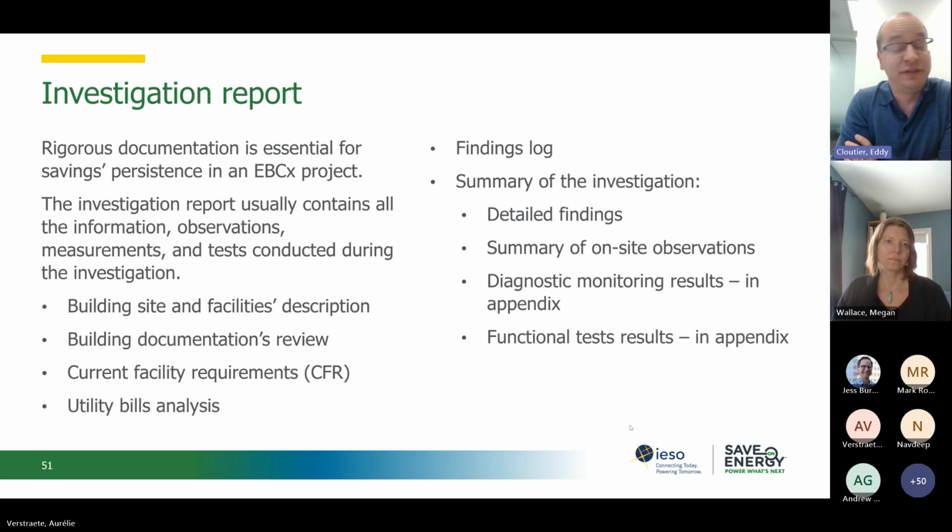The answer to that is it varies. It varies according to what type of BAS system you have in that specific building. Some BAS systems are more black box type, so more difficult to obtain data and to see the programming and the sequence of operation in the BAS system. In that case, it's more common to have participation of the BAS contractor in the investigation process.